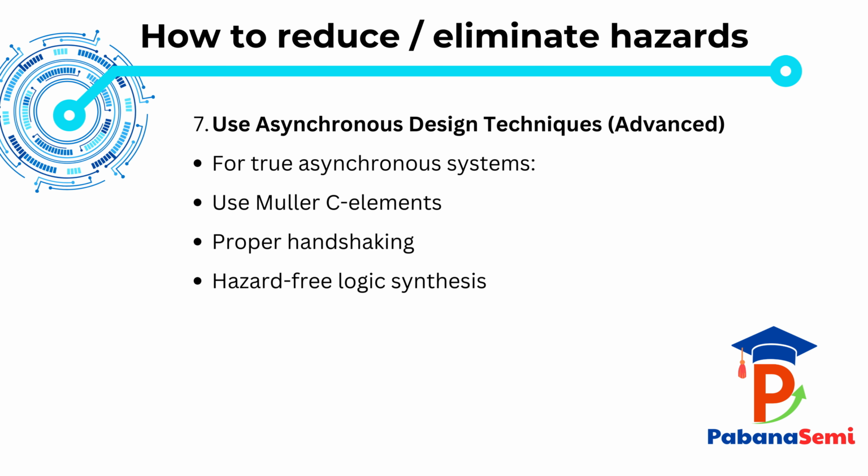Another key technique is proper handshaking. Instead of relying on fixed timing, asynchronous systems use request-acknowledge protocols. Signals are accepted only after they are stable and acknowledged. In synchronous systems, the clock protects you. In asynchronous systems, the logic itself must be hazard-free by design. That's why asynchronous design requires deeper timing discipline and specialized techniques.